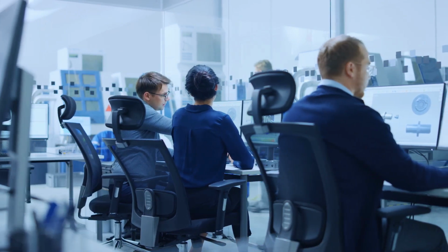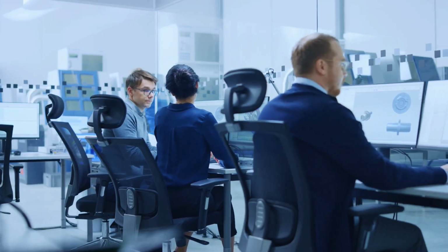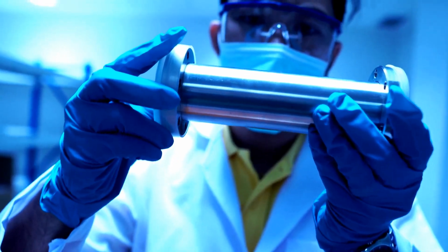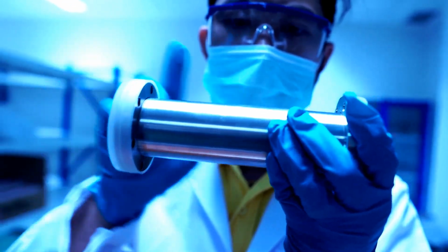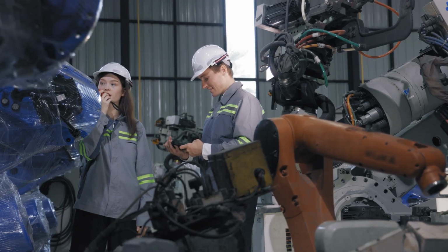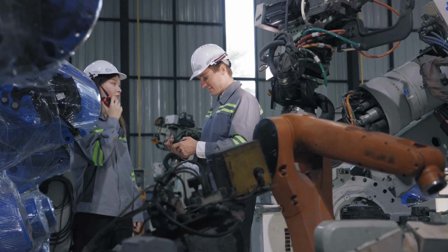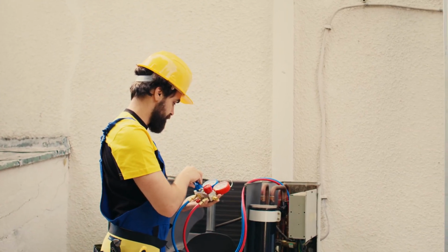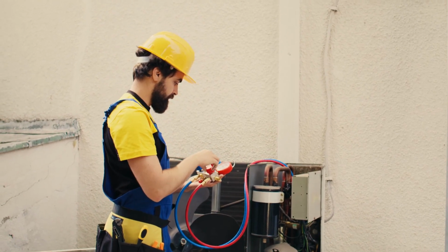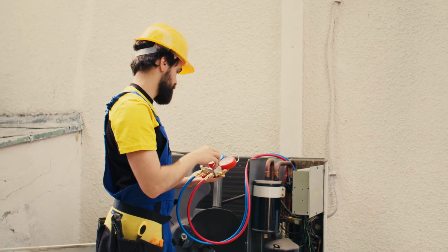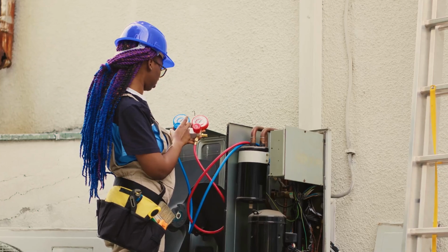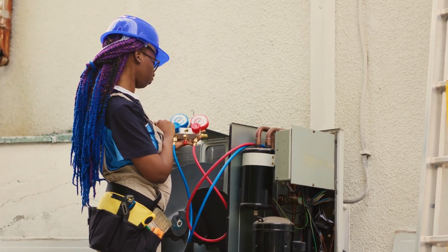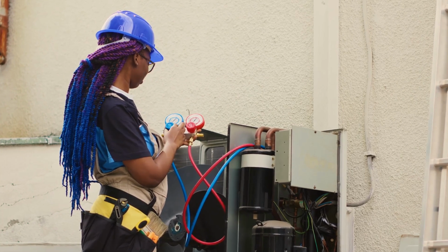Section 8. Real-world fixes from factories to software. Root cause analysis and corrective action are used in all sorts of industries, from manufacturing to healthcare to technology. Imagine a factory where a machine keeps breaking down. Root cause analysis might reveal that the machine isn't being calibrated properly, leading to excessive wear and tear. The corrective action could be implementing a regular calibration schedule and training operators on proper maintenance.